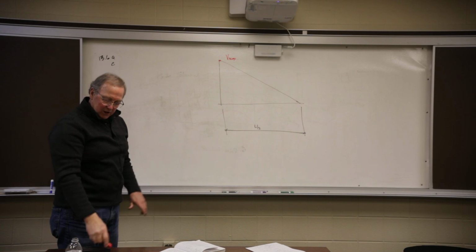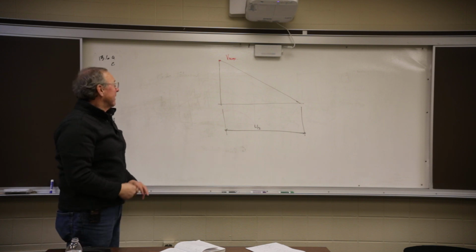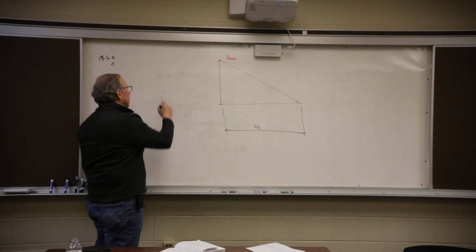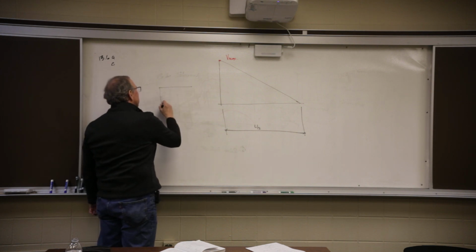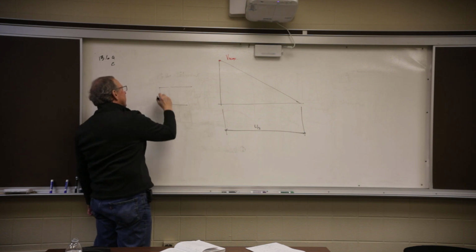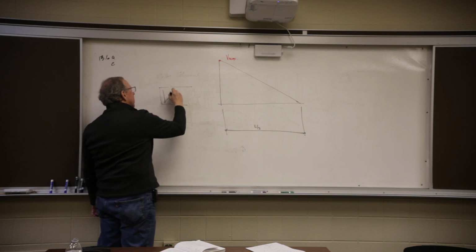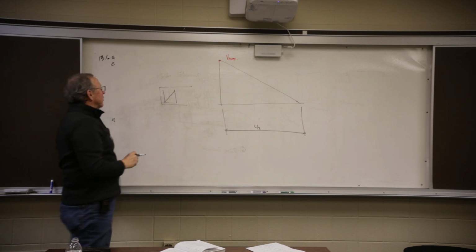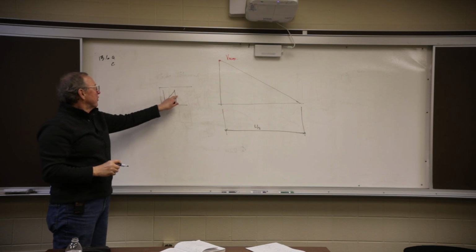Okay, code lets us relax that a little bit. If you look at a 45-degree angle, so I've got a beam, I've got a stirrup. If I go at a 45-degree angle, the spacing of the stirrup dictates the position of the next stirrup.